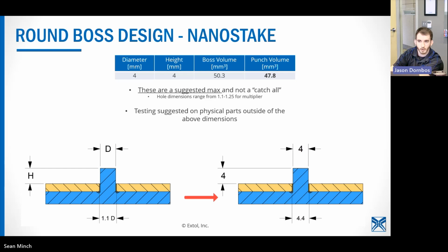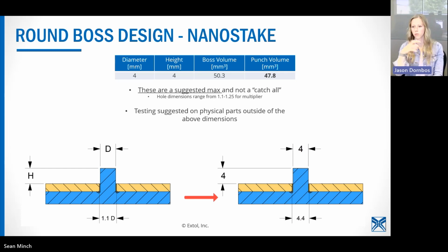Having that longer cross section of a tab versus a round shape would help with that. I think too, sometimes depending on the draw of removing the part from the mold, customers can't actually mold a solid round boss in. So we'll see some, don't we call it like a shark fin or something like that, when it has to match the mold or the draw of the mold.